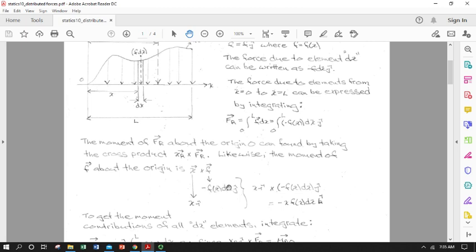So there's our area under our little rectangle at wherever it's positioned, however high it may be. It's in the y direction, and it's pointing down. So I can make a cross product of those two things. I can just do x sub i cross this expression. i hat cross j hat is k hat. I retain the negative, and now I just have the two magnitudes multiplied together.